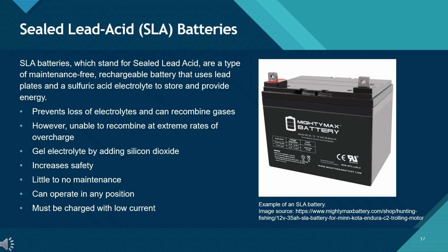However, they must be charged with a low current, and at very high overcharge rates, they cannot fully recombine gases. Overall, SLA batteries are practical, safe, and reliable for a wide range of applications.